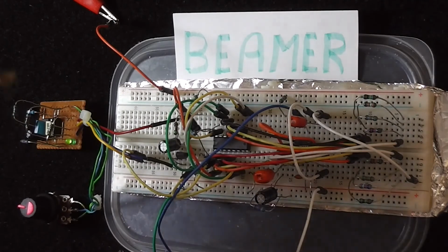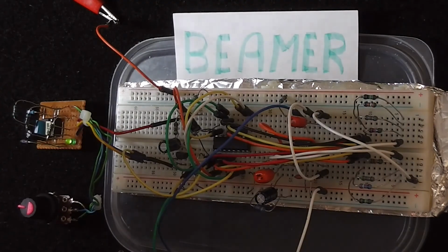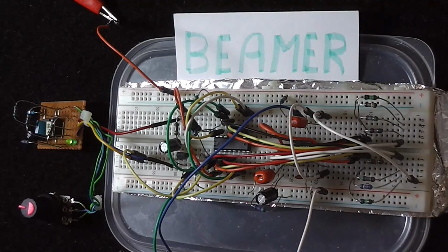So the 555 can, on its range 3, run up to quite a high frequency. That would be 480 kilohertz, which is the reason why I put it onto a separate board here, because at those frequencies this type of breadboard would fail miserably. So I moved the oscillator out onto a separate board, and of course for stability. Okay, moving along, we have the output dual op-amp, which is a TLC 272.